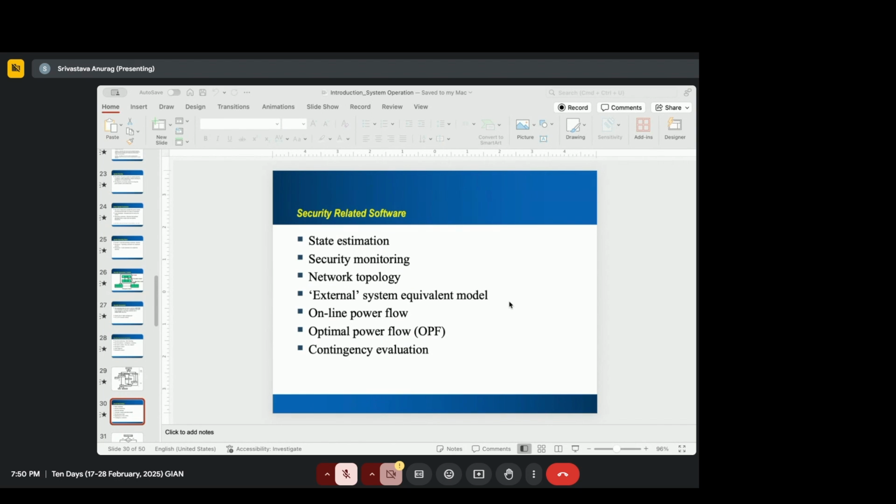Plus, it costs more money if you want to maintain the PMU at all the nodes and use the PMU measurement and integrate it with SCADA. So you can actually integrate the PMU and SCADA together. The only problem is that PMU is at a faster rate and SCADA is at a slower rate. So any hybrid analysis either needs to be slower or needs to be aggregated, or we keep it separate because it is reported at a different rate.